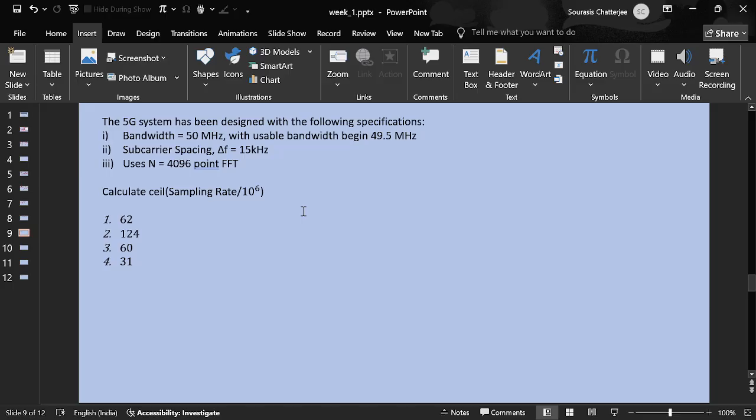Okay. So what is this idea of segmentation? Are you using a single carrier over the entire 50 megahertz bandwidth? Because then the channel is going to be frequency selective, right? There are lots of ups and downs, and as you pointed out, channel estimation and equalization are very difficult. So how do you mitigate that issue? Using multiple carriers. Using narrow bandwidth in this 50 megahertz, multiple such carriers.